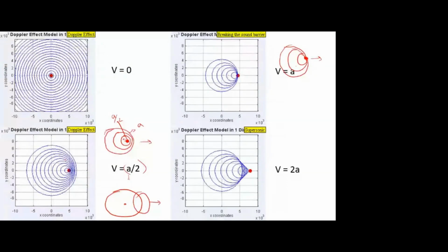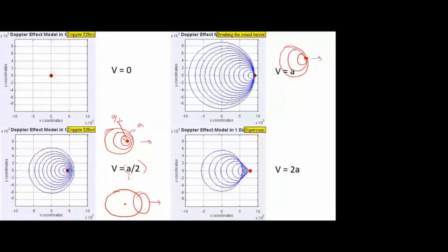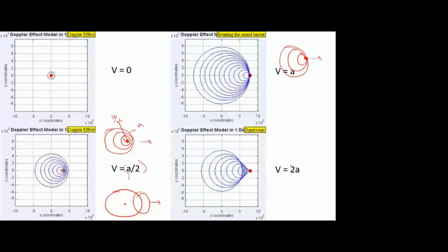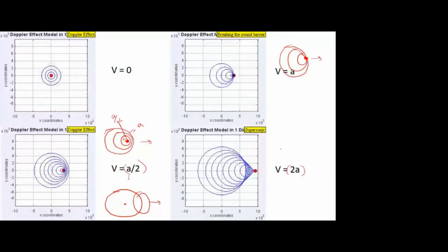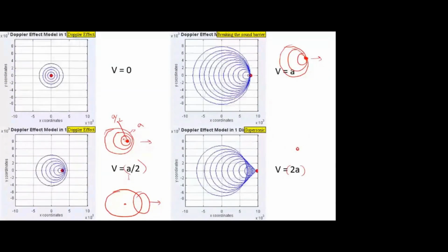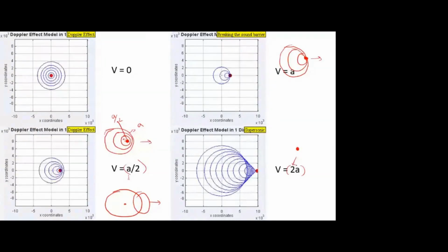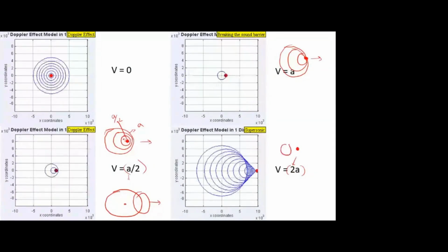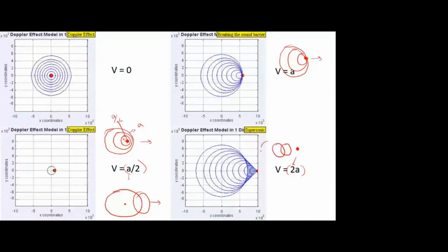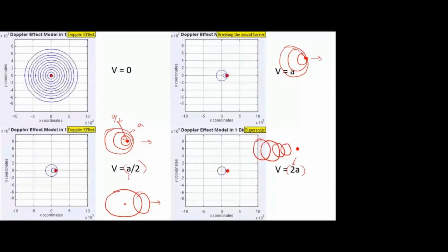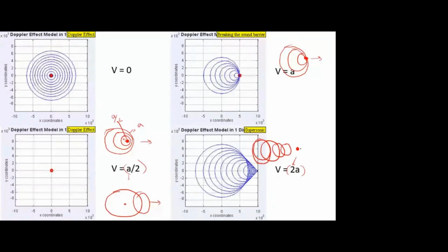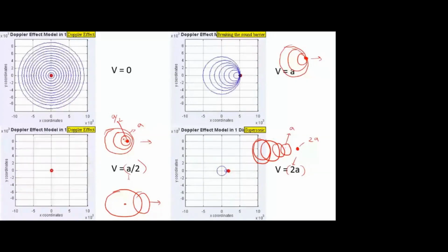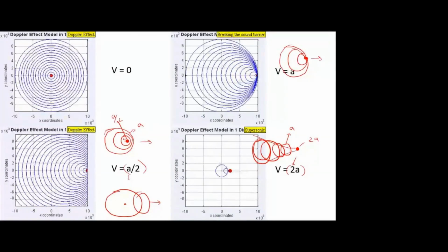So zero velocity, then subsonic, then the third one is sonic, then the fourth one is supersonic. Here the fluid element velocity is 2a, twice the sonic speed. The point disturbance velocity is 2a and it emits pressure waves whose velocity is a. After a few seconds, the pressure distribution, that is the wave distribution, will be like this. The point moves first because of supersonic speed and the waves come next because of the sonic speed. So this will be a cone-like structure.